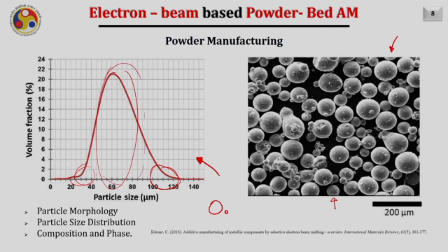The importance of having this small size particle and this large size particle in combination is to increase the pack density. If the pack density of the deposited or recoated layer in the powder bed increases, it will give us a few benefits, such as the conductivity of the bed can be increased and hence a few defects such as smoking can be avoided.